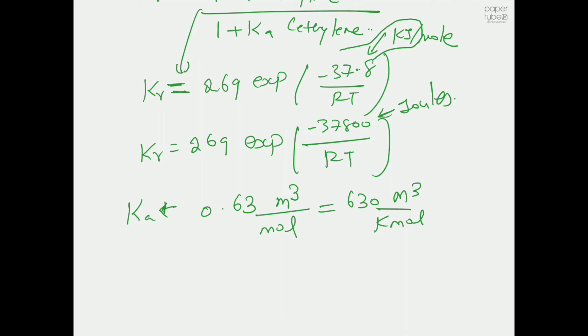Yeah, and why. So, if I use high temperature chlorination, I get a gaseous product. If I go for low temperature chlorination, I get a liquid product. And if I have a gaseous product, then I can connect it to a simple distillation column that allows you to purify the product without attaching a reboiler to the column. So these are the things that you should think about when you are going to design a project.